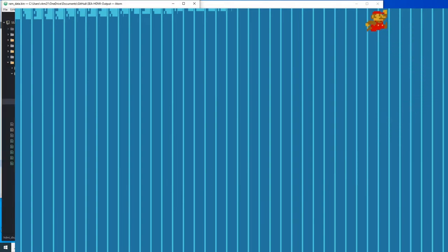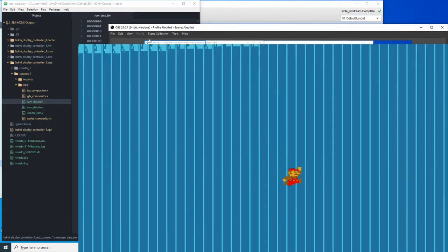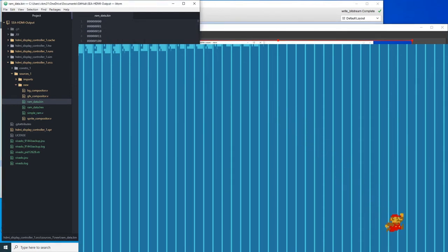All right. So looking at the data again, what we're seeing here is, if you look at our bits in the RAM, our first view is all zeros, then there's a 0 and a 1, then all zeros again. Because our first palette color is going to be static 1, the rest are all zeros, so it's 1 0 1 0 1 0 1 0 1 0 1 0 1 0, and then it should be 1 0 1 0, and then we jump forward 16 bytes.